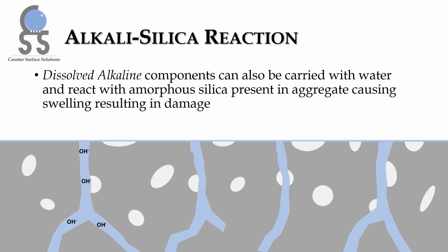The water penetrating into the pores can carry with it dissolved alkaline components from other parts, which could react with amorphous silica present in the cement, causing swelling and building up of pressure inside the structure and resulting in cracking. This phenomenon is referred to as alkali-silica reaction.